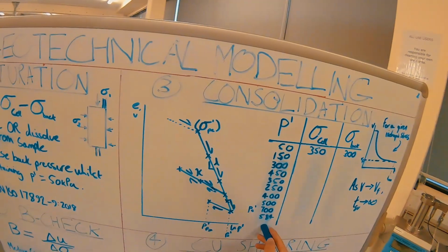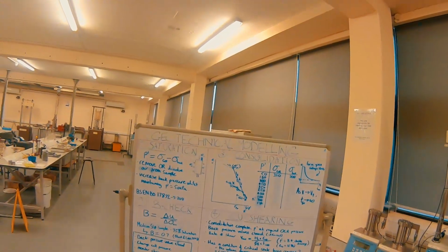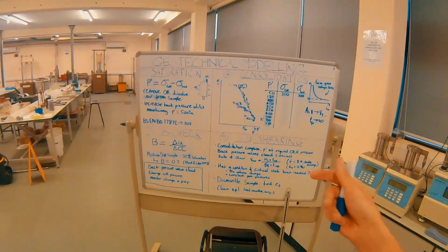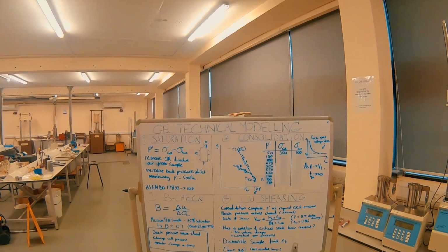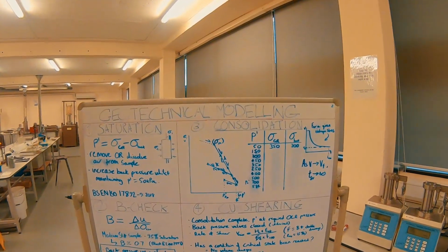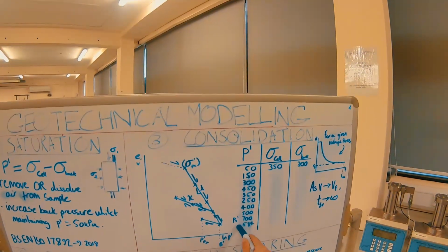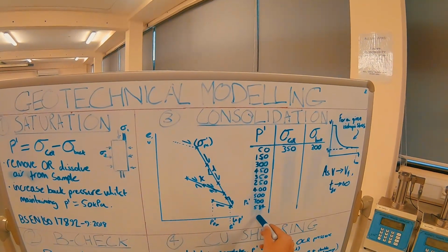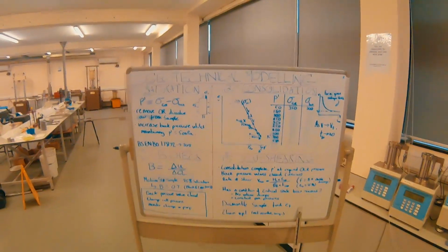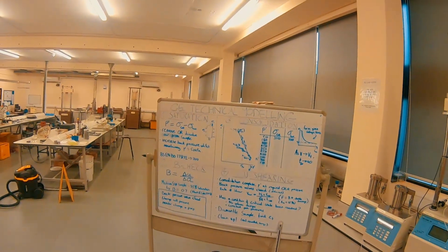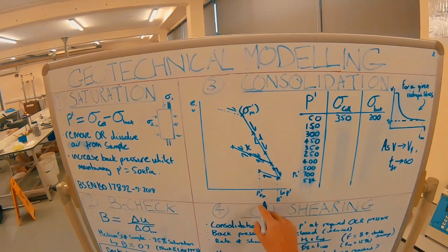And our shearing stress for this course, for this testing framework, is pretty much following the standard coursework that's given out to fourth year and master students here in previous years, where we're using an over-consolidation ratio of 1.2. So I'm dividing 700 by 1.2 to get this final P' value of 584, which is my over-consolidation stress. I've indicated that on this plot here by P' final, P' fin.